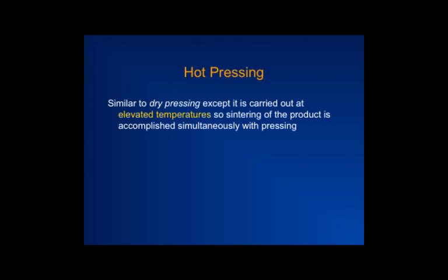No, you're well below it. Even in forming operations, right? You are not near the melt temperature. You might be somewhere between 40% of the melt temperature to 60% of the melt temperature. So it just glows red hot, but it is still only about two-thirds of the way at best to the melting point, right? But it has become soft enough that you can squish it.